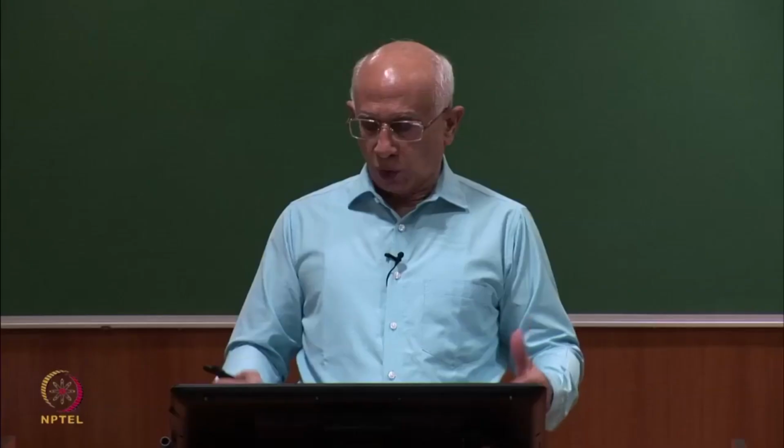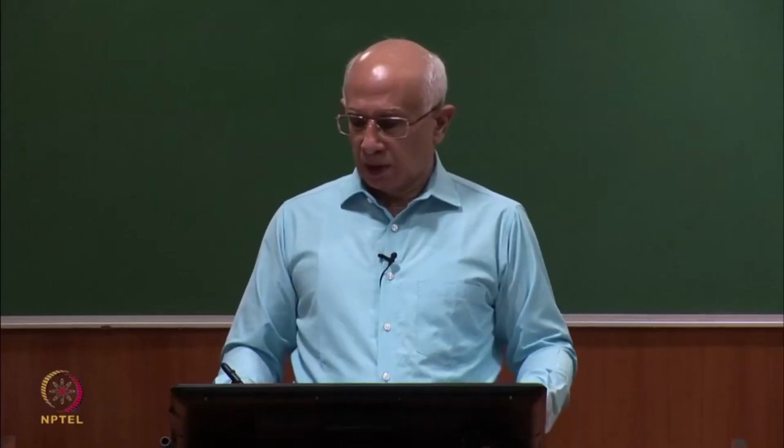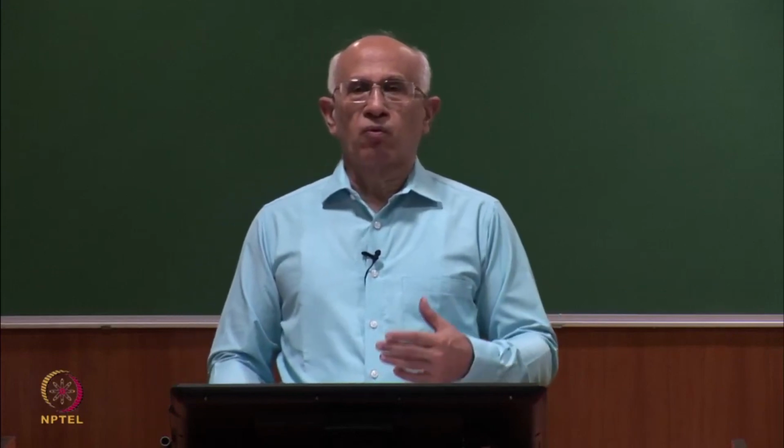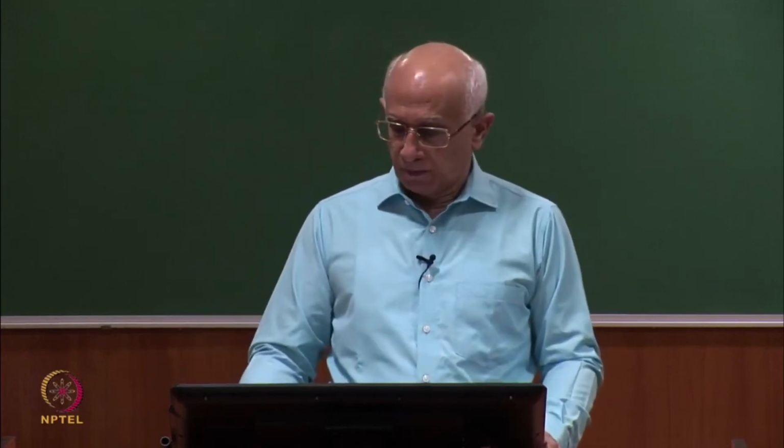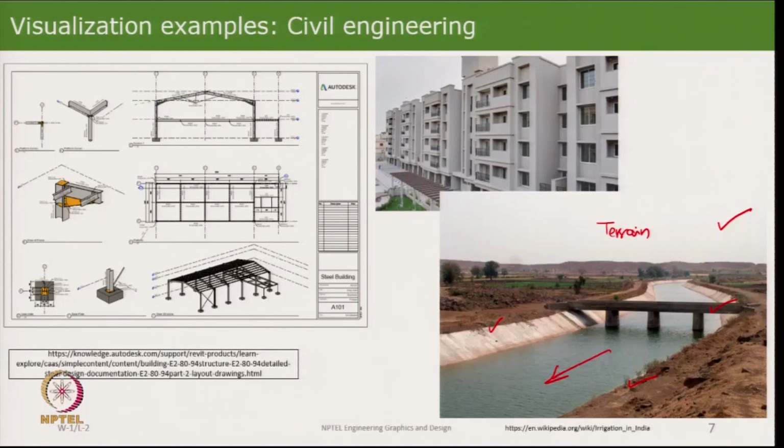Once it is made, those drawings and the pictures are the basis for doing regular maintenance. So, you need to look at the entire surface of the canal every so often to see if there is some crack in it, or something has come off, or weeds growing in it, or water seepage is happening, or the embankments have weakened. All of that needs to be monitored for the entire life of the canal, which could be 30, 40, 50, 60 years. So, that is one example.